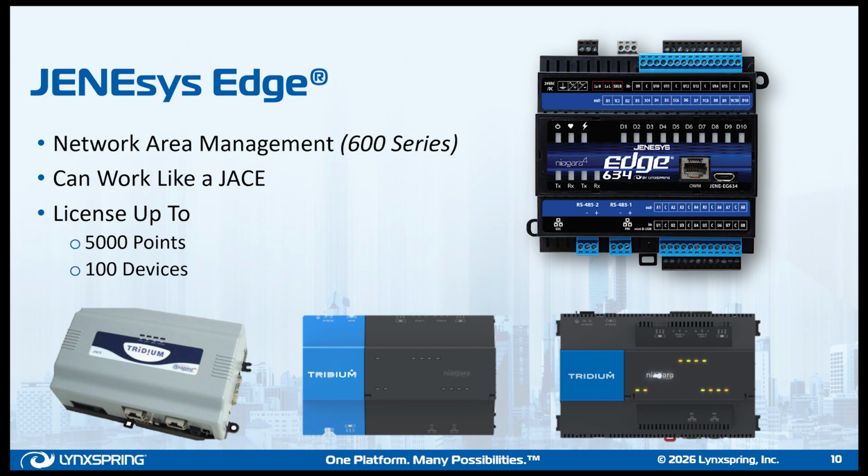The Edge 634 has the same software as any of those other ones, especially the JENEsys 9000 today with N4. It's not necessarily a substitute for a JENEsys, but can be considered in addition to, or as an alternate to it, because it offers hardwired I/O points, and it also has some onboard serial networks as well. It can be licensed to support 5,000 points and 100 devices. That is the license that the 634 can offer you if you need it.